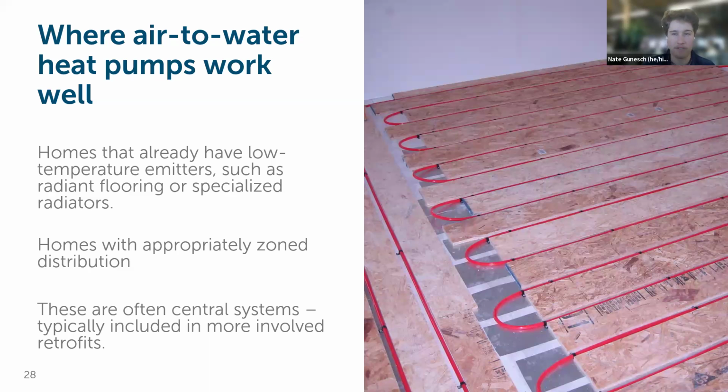But work with a professional, right? There are contractors out there who know how to do this work really well, know how to zone the system, know how to distribute the system well. So if you're going for a high level of design, a high level of work with a specialized contractor, you have to get the appropriately zoned distribution, right? So I mentioned that earlier. I sometimes overlook that when I say to people, hey, radiant slab means you're a plug and play opportunity for an air to water heat pump. Technically, you also need some appropriate zoning.